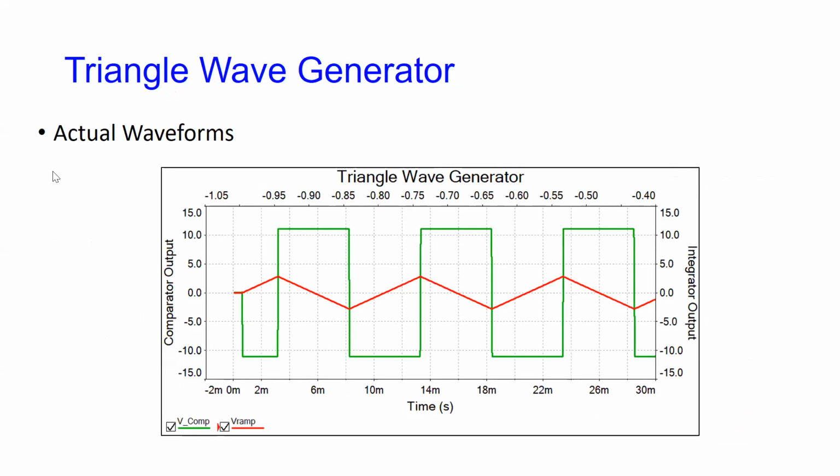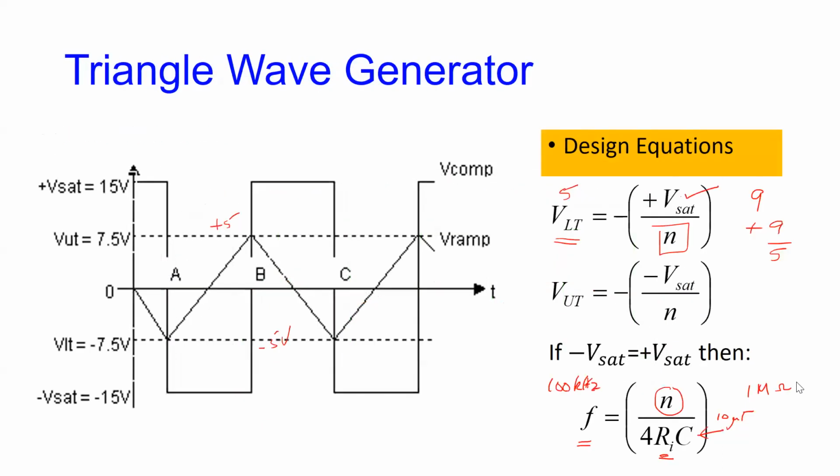Okay, so where are we? It's a very straightforward, very, very easy thing to design and to get any sort of frequency. Typically, 100K is probably about the highest you would get with a 741 op-amp. If you start to go higher, you get this kind of behavior, looking like that, if you try to go to too high a frequency with a regular op-amp.